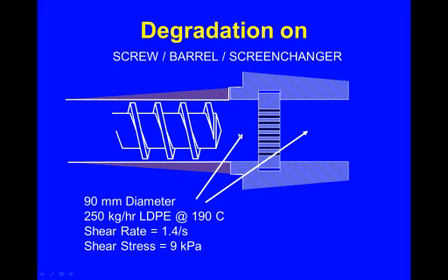So for example, at the end of the screw we have a screen changer, and quite often when people add screen changers to extruders, the screen changers typically require some distance prior to the breaker plate for the pressure in this area to load the seal section. There's usually a sealing section in here, and it requires some distance to create enough force to create the seal.